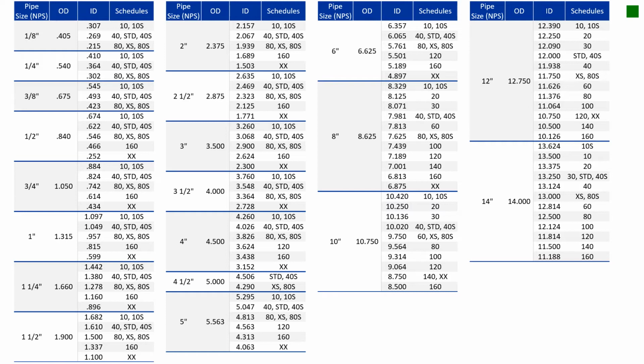Now that we have looked at the friction factors, we notice that they're a function of the Reynolds number and the relative pipe roughness. Both of those require knowing what the inside diameter of the pipe is. In the United States, we have various different types of piping which have different wall thicknesses. And we separate the wall thicknesses by something which we call schedules.